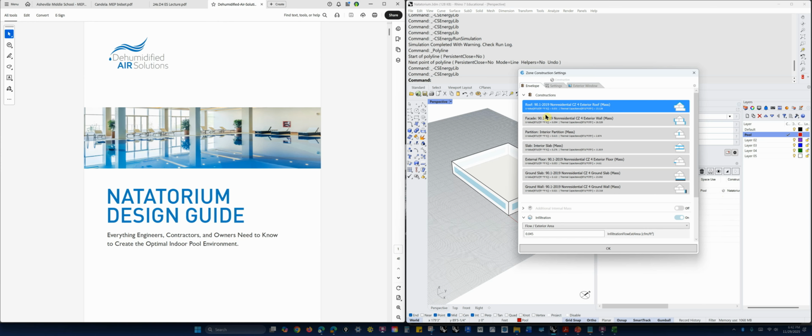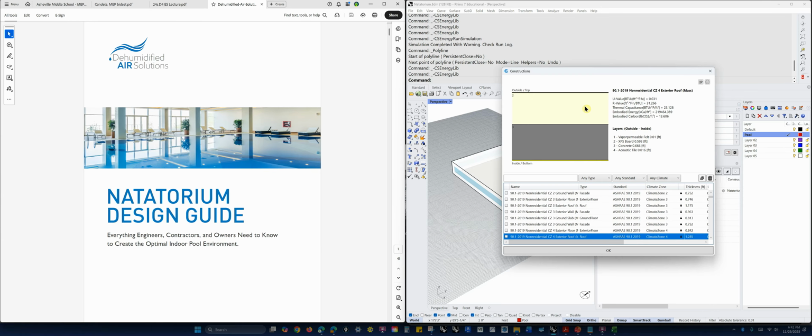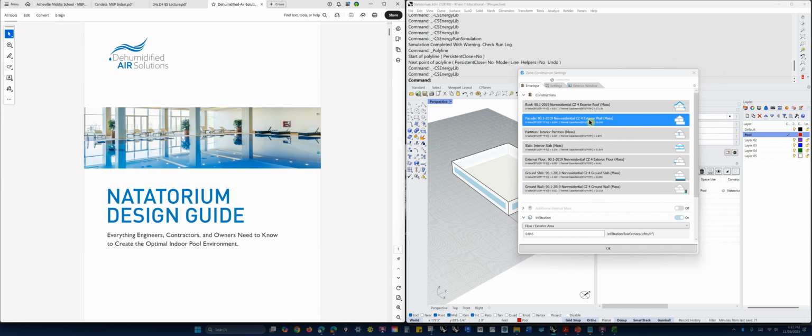Then I did create a construction template. The basic idea here is kind of common sense, well, maybe at least to me. We need to use materials that are resistant to water, and so I did a mass roof, it's concrete with insulation on top of it. I also have a mass wall, so I'm thinking about concrete or concrete block or something like that. I have a very low infiltration rate. This is definitely passive house level. It'd be hard to do.